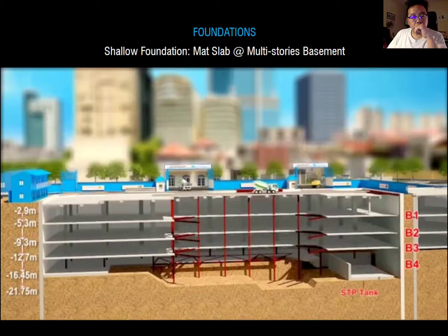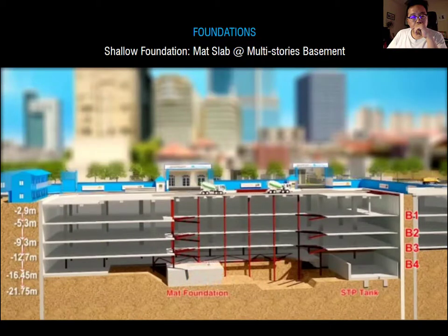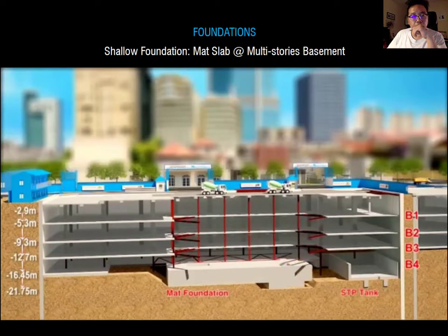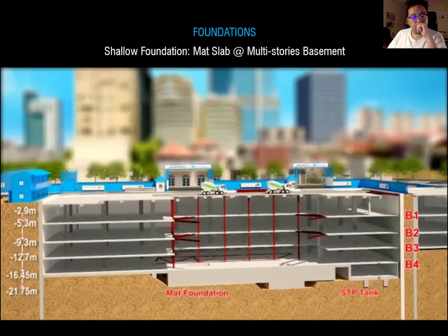Reinforced concrete for mat foundation in single pour by using the low heat cement in combination with using the new generation plasticizer to minimize water demand and optimize mixed design components for controlling the temperature. Reinforced concrete of basement 4 slab in the remaining areas.